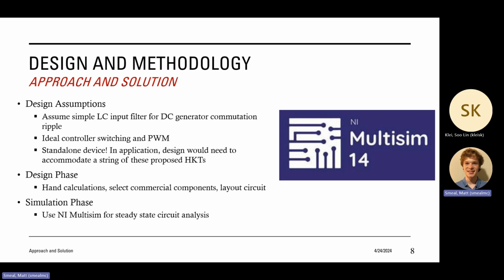So for the design phase, we did standard calculations. We selected commercial components that were available on National Instruments Multisim version 14. And then we just laid out the circuit and ran a steady state circuit analysis for the simulation phase.